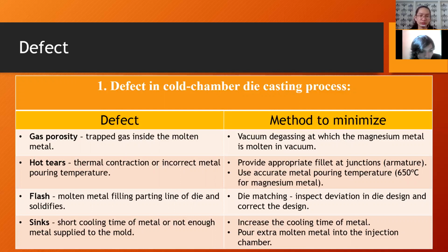Another defect is sinks. They are caused by a short cooling time of the metal or not enough metal supplied to the mold. It can be minimized by increasing the cooling time of the metal or by pouring extra molten metal into the injection chamber.